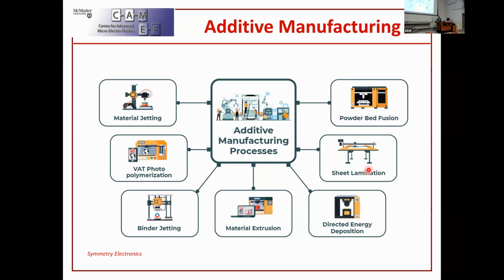So all of these in some form or the other got started in the 80s. And the driving force behind them was this new technology at that time, which was photolithography. So photolithography is basically you make 2-dimensional masks and create patterns onto flat surfaces, and then you slowly try to build it up.